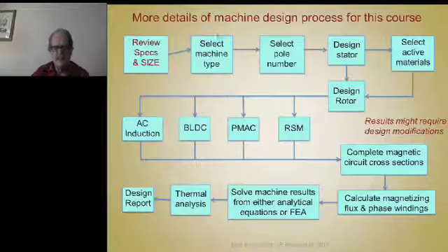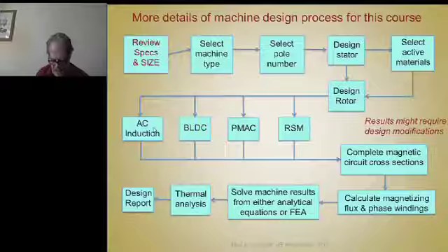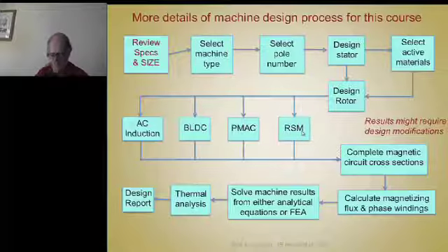In the case of the induction motor, your peak torque determines the maximum magnetizing flux and the maximum magnetizing current. So in the rotor design, you have to balance the cross-sectional area of the copper for the cage with the cross-sectional area of the steel to carry the flux for the peak torque. That's the key. And now the reluctance synchronous machine has flux carriers and flux barriers.